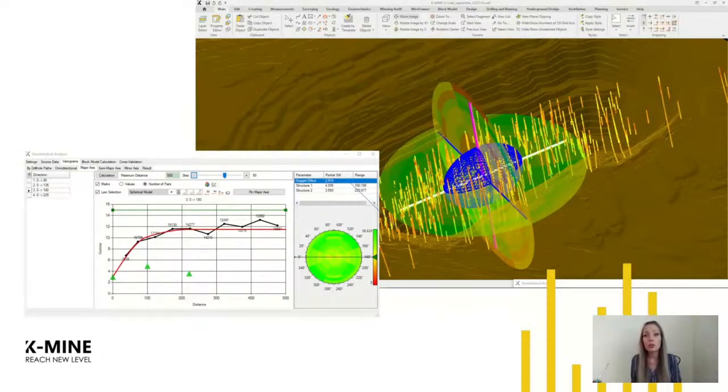So that's where software like K-Mine is useful. Today, people usually assess resources using mathematical, statistical, or geostatistical methods, evaluating the accuracy of the estimation. This method takes into account contouring and resource estimation options and the errors of all variable parameters like errors in determining thickness, content, and so on. K-Mine can integrate the entire deposit data area into a single space for detailed analysis and improve the accuracy of the interpretation of the geological structure, especially in the detail areas between exploration intersections.